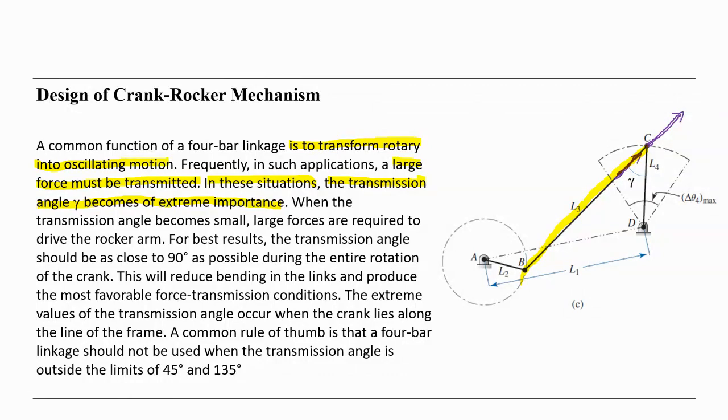The important portion of this force is actually the perpendicular part, perpendicular to this rocker, because this is the driving force. And this component, the vertical component of this force, is going through the fixed point here, the bearing.